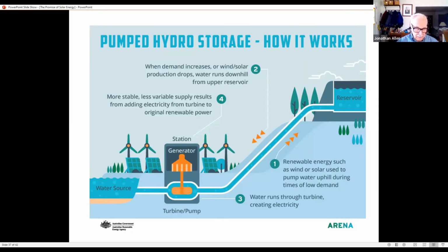There are problems, however, because when you compress a gas, much of that energy goes into heat. Just feel the bottom of a tire pump when you've been working it for a while. If the storage system dissipates that heat before you get the gas back out, that's waste. So the estimated round-trip efficiencies range from 40 to 70%, the lower value being largely the result of heat loss.